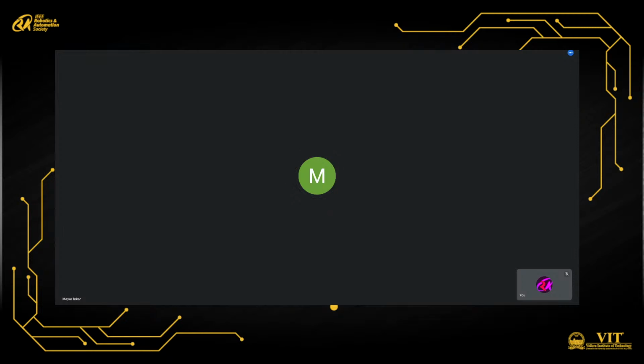To control different processes, you don't have to build different circuit boards. You just have a single component, a box, a PLC, in which only a single motherboard is available, which is controlling the entire machine, and even an entire panel or an entire plant. A single PLC can control it, but it is different with the Arduinos and other controllers. For each and every process and each and every automation, you will have to design a circuit board, design a component over it, and manufacture it. You have to repeat this for each and every process.